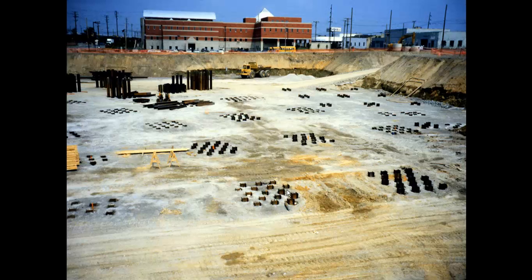So you can see what they've done is clustered these piles so that they'll cover these with some kind of a plate for bearing capacity, and these are probably at a location of a column or some type of support structure that's going to take the main load of the building. You can see these are all in place and have been cut off. These are still sticking up above the ground. They haven't been cut to level.